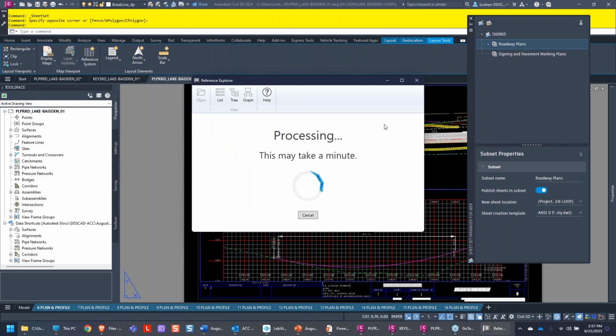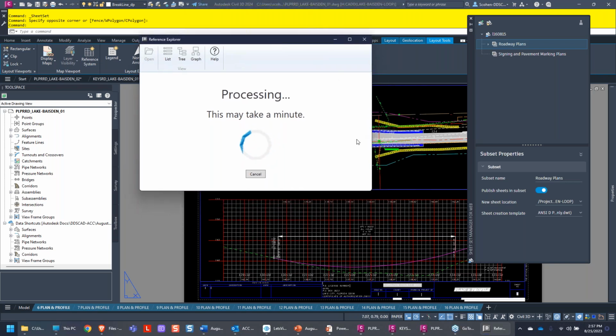What it does is it actually reaches into the file and interrogates it and says, okay, what references are being used. So in my opinion, what you can do is, I don't necessarily say detach them, but make sure they're all relative and keep your subpaths the same. That way, when you upload it, it should create folders and put them in there for you automatically. That way you don't have to worry about it creating new folders or putting them somewhere totally different.